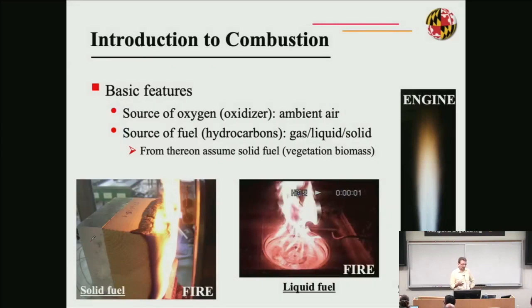So for us, I'm just going to go for the next few slides that try to put the combustion problem in fire into a wider framework. But for us, combustion is an oxidation reaction between hydrocarbons that are produced by solid fuels. So the picture on the left is the one that is relevant to us for wildland fires. We're going to assume that the oxygen comes from air, and that's the case for wildland fires. And so again, these hydrocarbons are initially present in solid form, and so you need a phase change process, this thermal degradation process, to take these hydrocarbons from solid form into vapor form, so where they can burn in the flame.